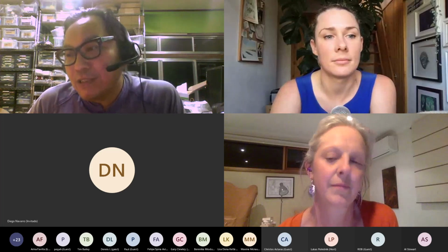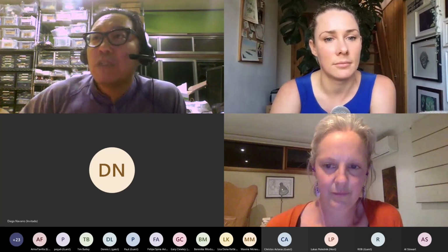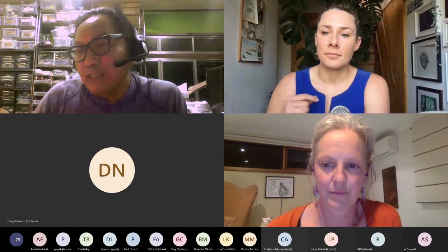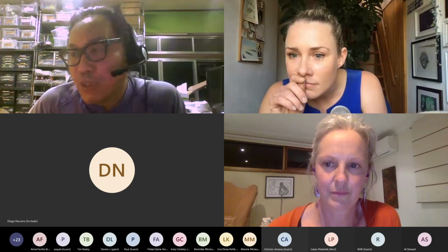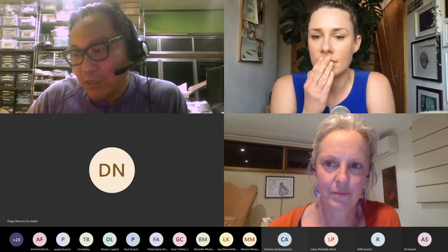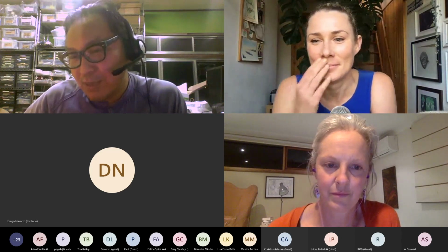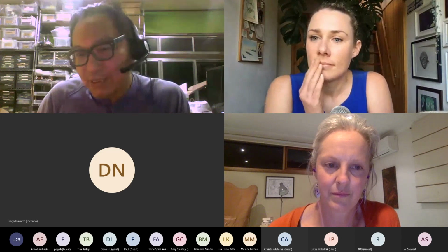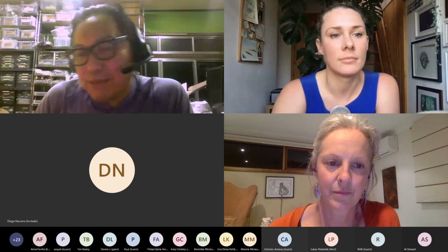The SD card uses quite a bit of power, so if you need to go a year in the field on 3 AA batteries, you'd want to go into something like chip memory, solid state memory, a non-SD card based one. That's something we can talk about too, if you have specific questions later on.